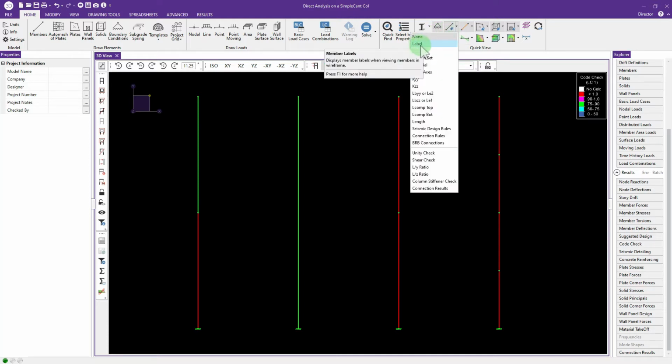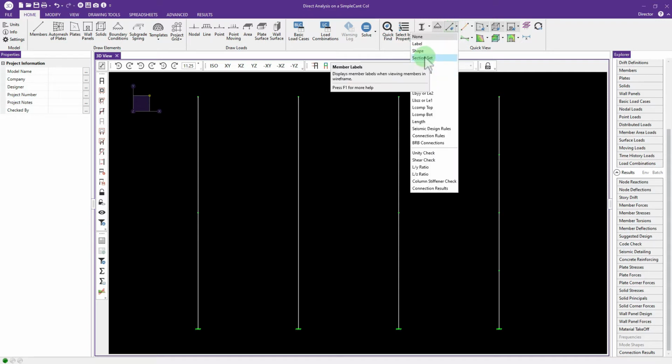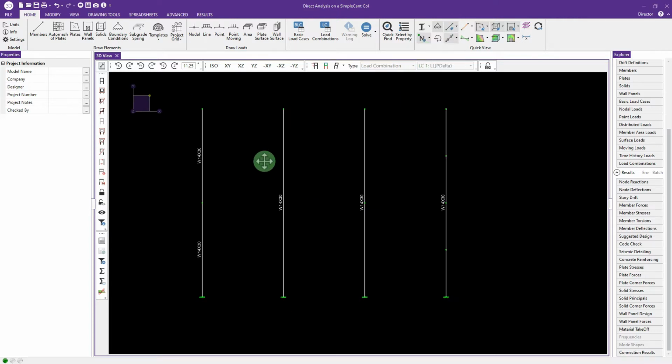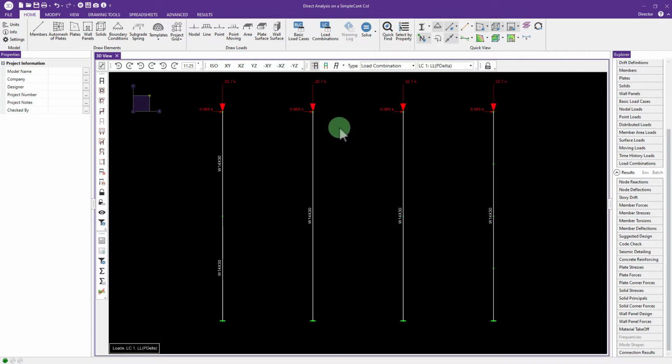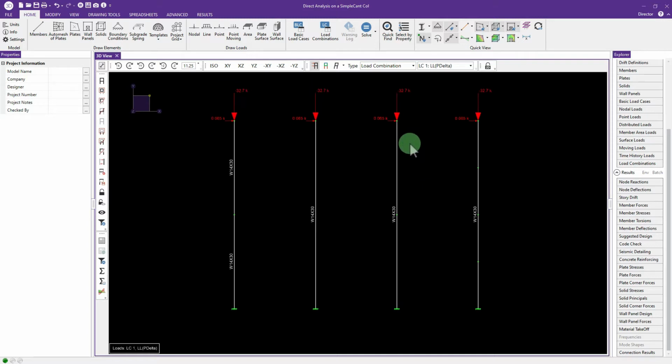So what I did was recreate the models from start. Just go ahead and show nothing here and turn on some of our section sets. Actually, turn on the shape, and I recreated the exact same model that I had before of a W14x30 that's 12 feet long and is loaded to what I know to be the calibrated capacity of it as far as allowable strength design method is concerned, using the direct analysis method.